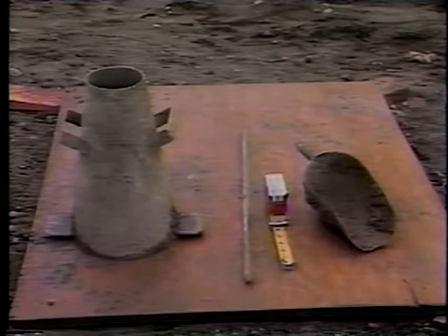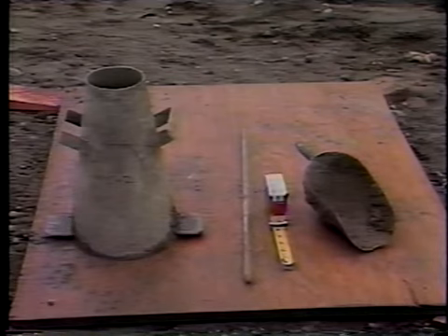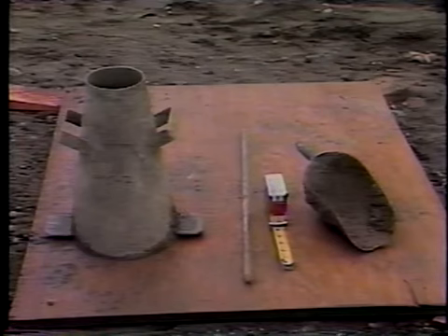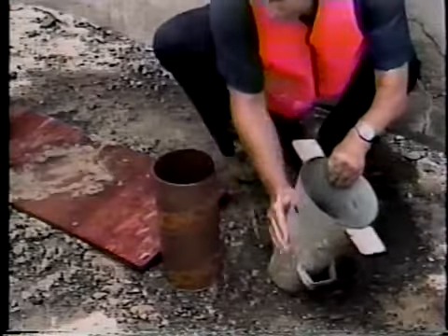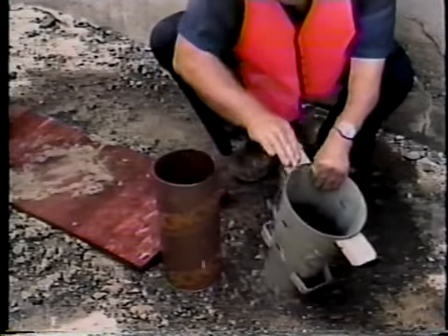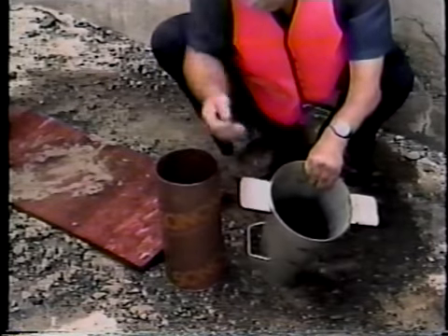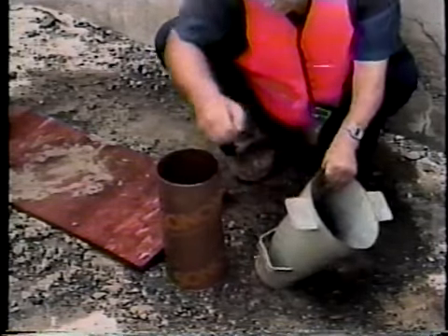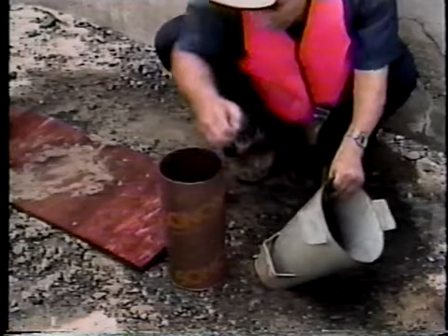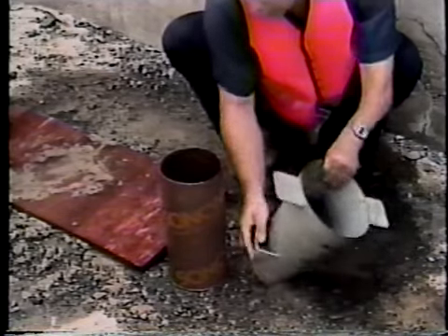The equipment needed for slump tests includes a standard slump cone, a standard tamping rod, a scoop, a base, and a ruler or measuring tape. The slump cone should be reasonably clean, especially inside. The surfaces should be smooth, with no dried concrete on them. Also, there should be no major dents.